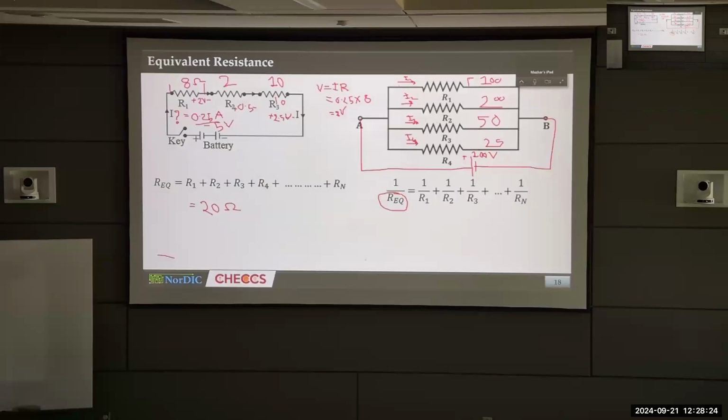So as you already have the idea how to calculate the current across a parallel assembly like that, the values are basically you multiply the voltage difference between these two resistance divided by the value of the resistance. For example, here the voltage difference across all of the resistances is the same, since their terminals are connected in the same node, right? The same terminal. So they have all 100 volts in their two terminals, but they have different current because of their resistance values, right? It's nice to look who got the most of the current.